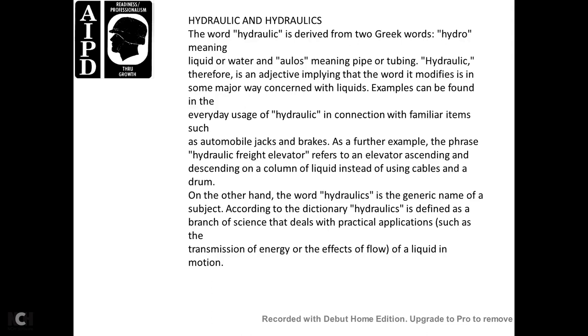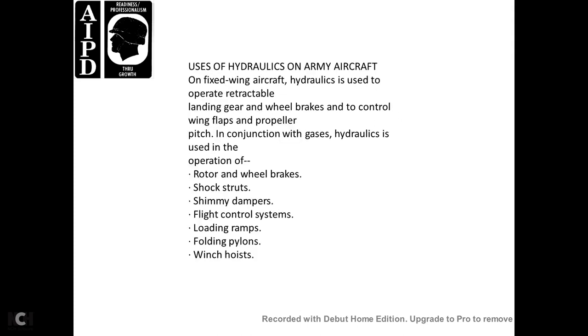On the other hand, the word hydraulics, the generic name of the subject, is defined by the dictionary as the branch of science that deals with practical applications such as the transmission of energy or the effects of flow of a liquid in motion. Use of hydraulics in Army aircraft. In fixed-wing aircraft, hydraulics is used to operate retractable landing gear and wheel brakes, and to control the wing flaps and propeller pitch. Hydraulics is also used in the operation of rotary-wing aircraft, wheel brakes, shock struts, shimmy dampers, flight control systems, floating ramps, folding pylons, and winch hoists.